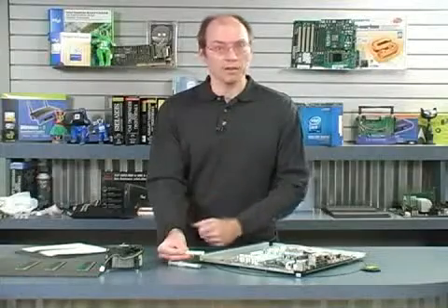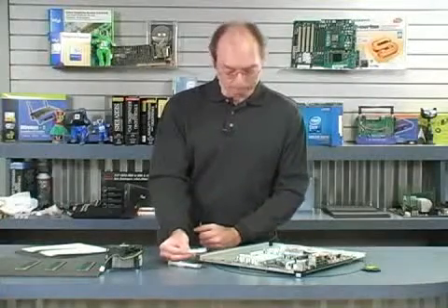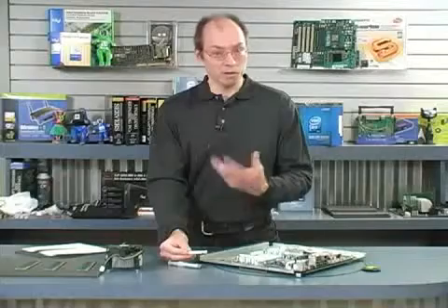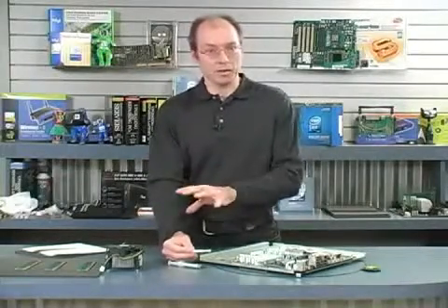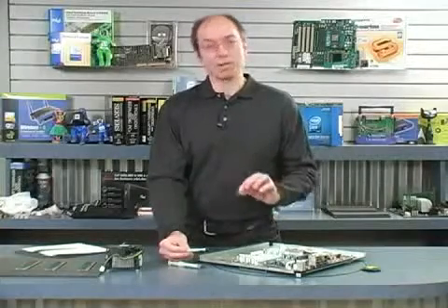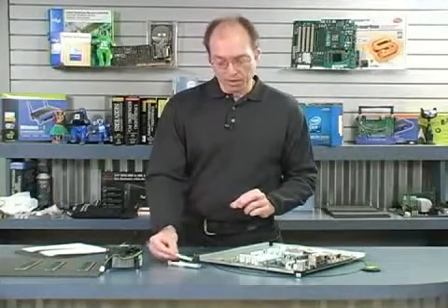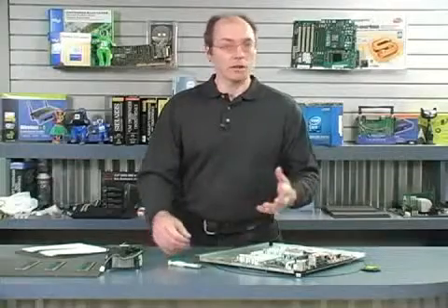They just give you enough that you can get it properly installed at least one time. Now, this stuff is a grease. What are the differences between that phase change material and the grease? Well, the grease has a couple of problems that the phase change material doesn't have. One is called pump out, and the other is called dry out.